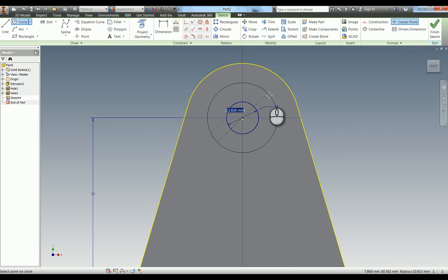And then we've got our outer one, so I'm going to put the circle down. I could put in the diameter of that, which is 22, or the alternative thing you can do is you can put a distance in between like this, and we know it's radius 3, so it's 6mm. So now we've got our two outer, our ID and our OD.